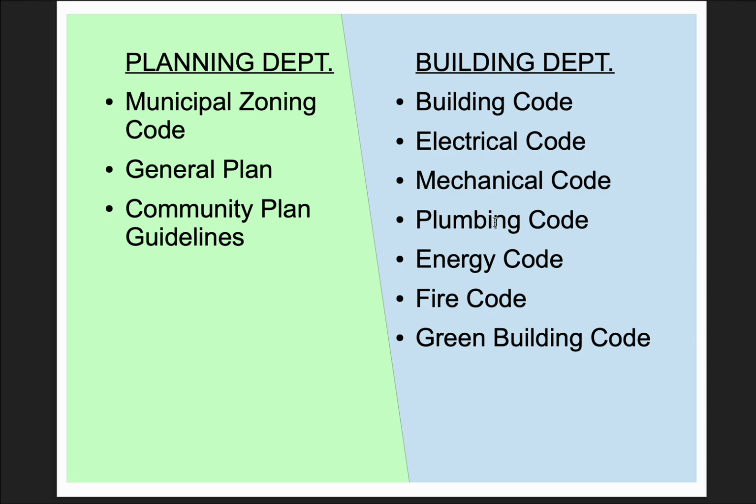Typically the mechanical and the plumbing are just one consultant. Fire sprinklers would go through your plumbing, and the mechanical consultant usually handles ductwork and plumbing at the same time. And they have to work closely with the energy code, where their equipment is energy efficient, and their lighting equipment or lighting bulbs are actually energy code compliant. For some occupancies of building, which we will discuss at a later time, they also have to see that it meets fire code. For institutions or commercial buildings of certain size and occupancy, there is a need for sprinklers, and the fire code explains that too.